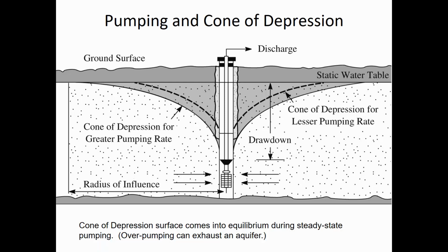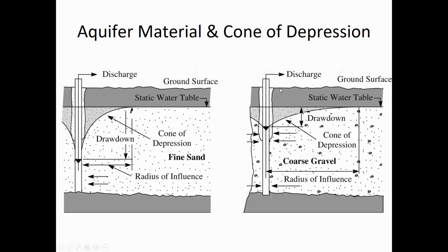So I'm not sure what they're dimensioning that drawdown to, because the lowest water surface appears to be here at this location in the well. So the drawdown at the well would be from where the static water table height was before pumping started to the water surface in the well. But at some distance r, a radius from the center line of the well outward, you can measure the drawdown. And the further away you get from the well casing, the less the drawdown is going to be.